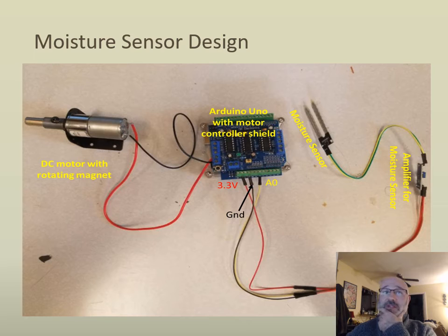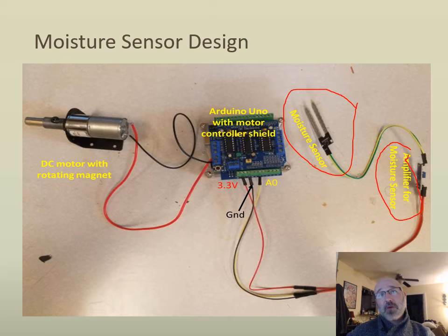Taking a look at some of the physical hardware that we have here, here is our moisture sensor that we're going to place in the ground to measure the properties of the soil. Here is our amplifier right here. This is what we talked about. We can adjust that gain manually on that amplifier to set our threshold values for what we consider levels that are too moist, or too dry, not enough moisture content. All that information can be adjusted by this here.